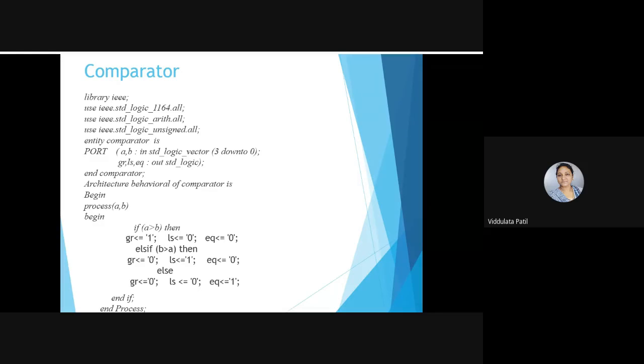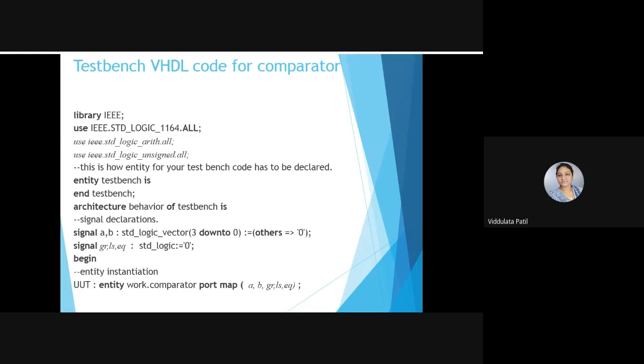Now, as you have seen while actually using the Xilinx ISE software, when you write a test bench for any code, we need to associate that code with the test bench, and when you do this, the library declaration and entity declaration parts come automatically.